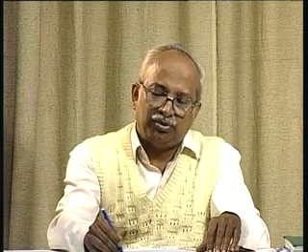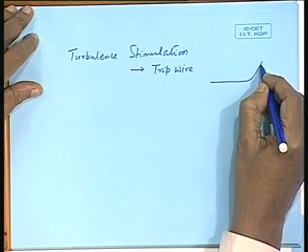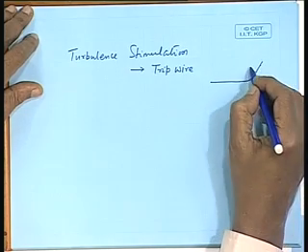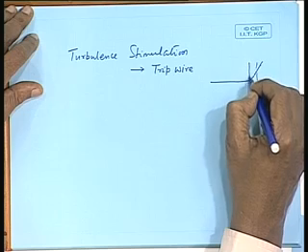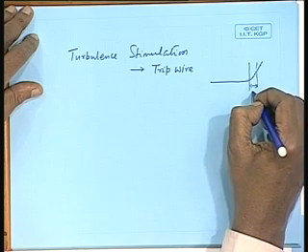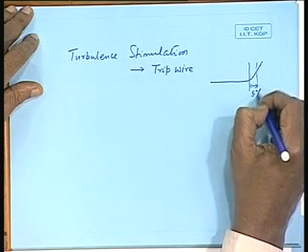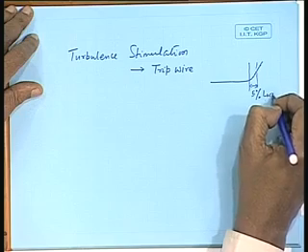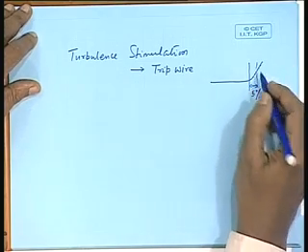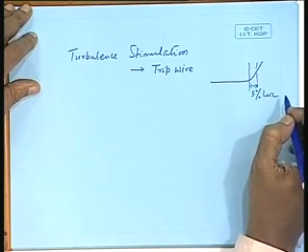And what we use is called a tripwire. This is the normal turbulence stimulator used in ships. That is, I got a ship model here. I can put a wire right on the front of the ship, or if this is the FP, about 5% length aft of FP, LWL, length on water line. Normally in model tests we use length on water line.